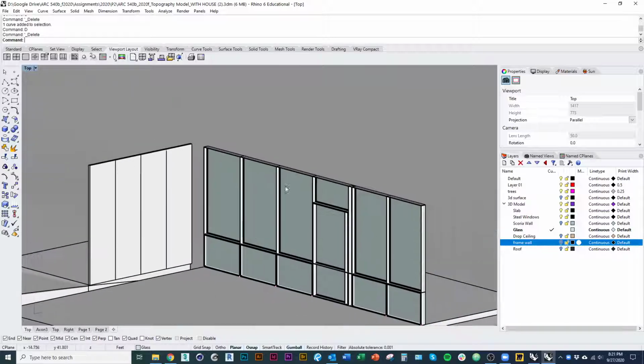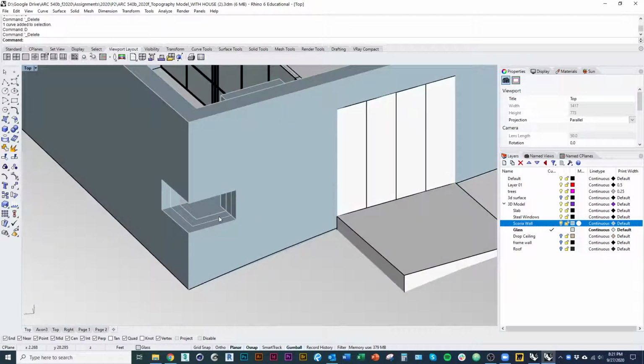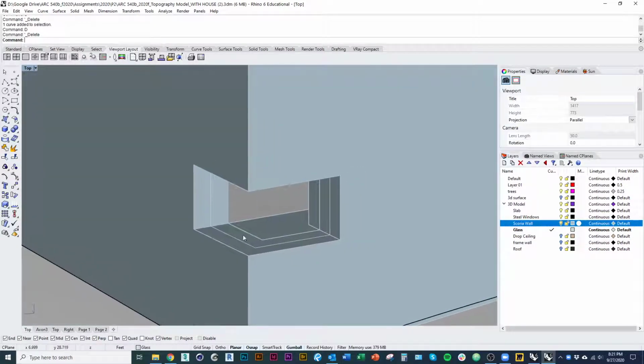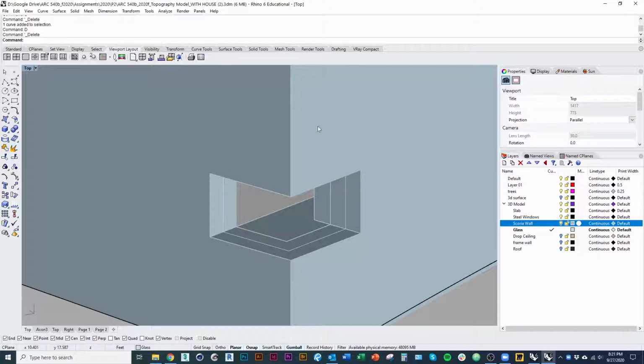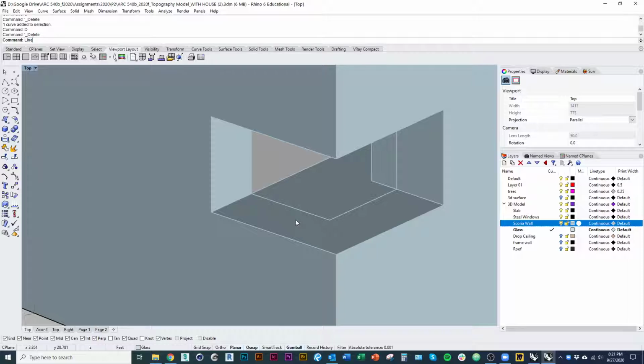we have the glass wall completed. So I'm going to turn on my scoria wall and map out where my window framing should go. I'm just going to use a curve to start off with. I'm going to use the command Polyline, and I'm just going from the midpoint of the wall. I can work in whatever direction I need to if I have those dimensions.